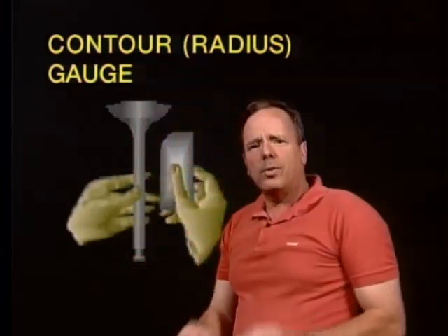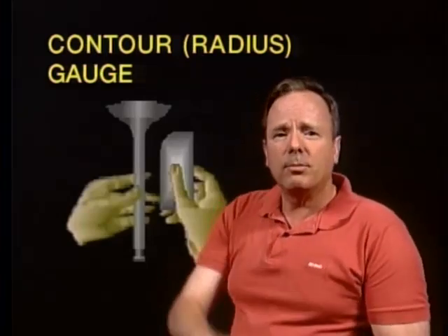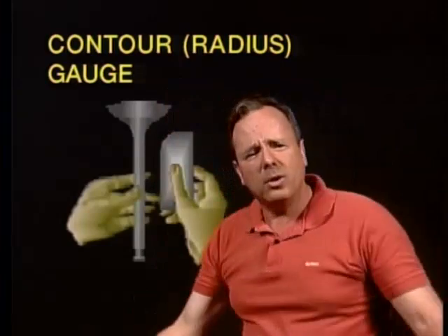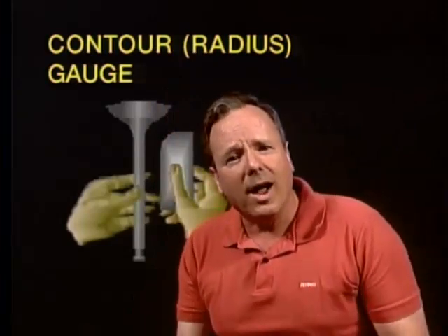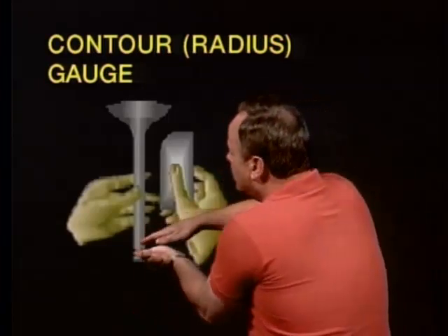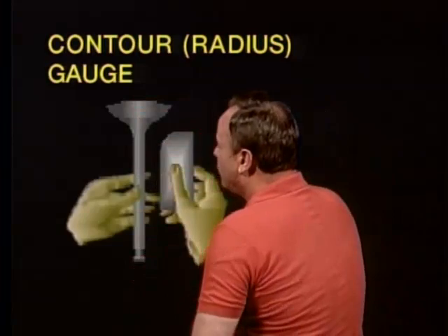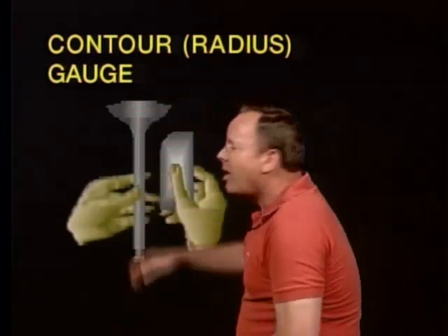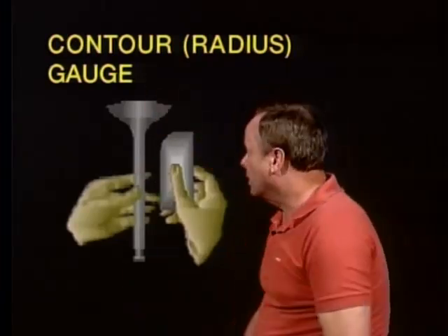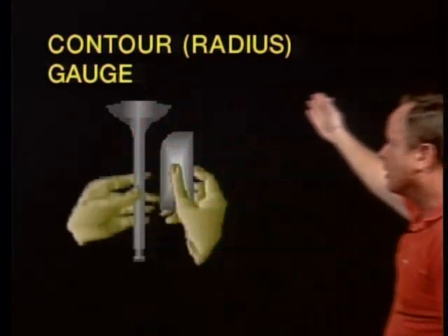Now, we know that's the correct answer, that you're not allowed to measure the length of it. We've checked with several shops. They say, well, could you measure the length? They say, oh, no, you can't do that. And then we ask them why, and we don't know. It's just not an approved procedure to measure the length of a valve. So if you want to know if a valve has stretched, you use a contour or the same gauge with another name, the radius gauge.